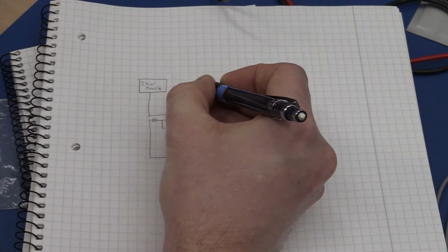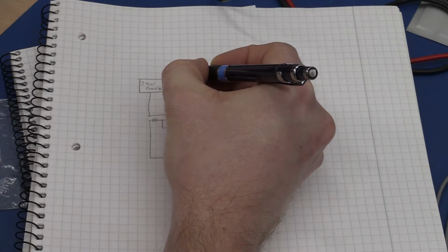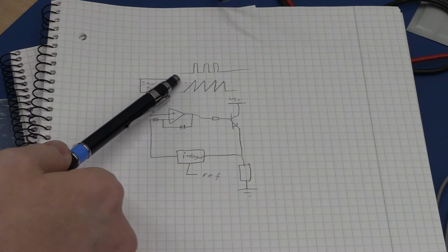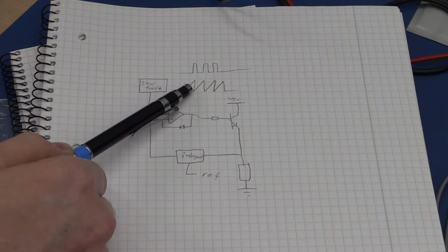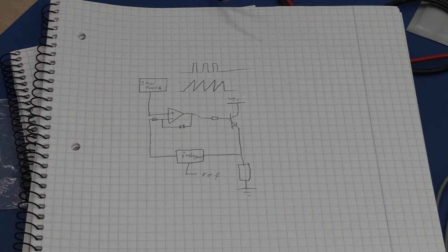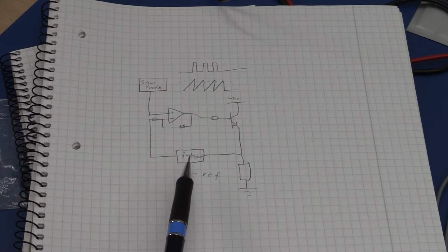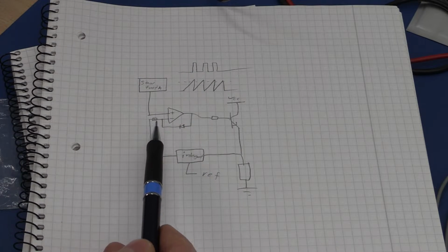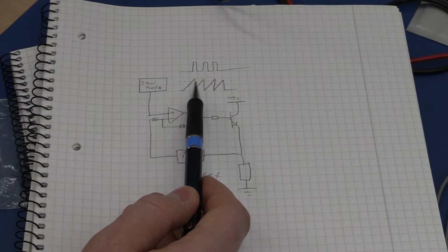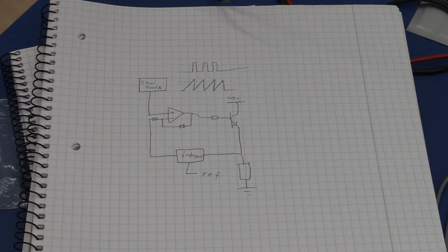Over a short period of time, the output here will look like a horizontal line. And if we compare a horizontal line to a sawtooth wave, you can see we will get a PWM signal. Say we have the line here. That means basically we get a high every time the sawtooth is greater than our reference here. The diode here shouldn't really be necessary if we use a proper integrator here, because the response should be slow enough that it will be cut off by the sawtooth.